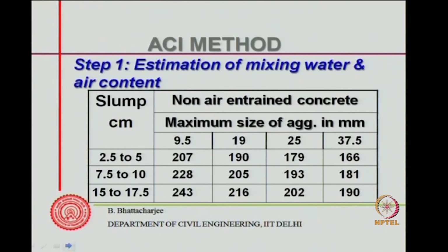This table has two parts. The first part is related to the mixing water, and the second part gives you the amount of air entrainment. So, you determine the air content and mixing water together from two tables.